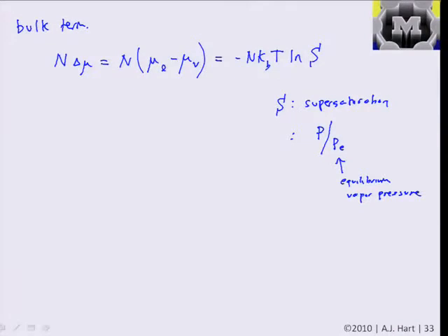And the idea here is that if we control the conditions so we supersaturate the atmosphere, so we have more vapor than there should be in equilibrium, then it'll be energetically favorable for the vapor to condense into droplets or condense into clusters and for us to start forming nanostructures. And the same thing can be applied qualitatively to having them in the gas phase or having them on a surface, where we're now, instead of saturating the gas phase with precursors, we're saturating the surface with precursors, and we're starting to form clusters.